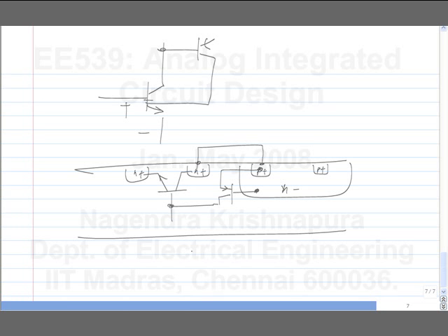If you have a large drop across this, let's say this is grounded, then this will get forward biased and that will turn the latch on. That's why as you go to newer and newer technologies, you have smaller and smaller components, but you also have higher and higher doping in the substrate so that this won't happen. Okay. So when you deliberately forward bias junctions that are not supposed to be forward biased, it could potentially lead to latch up. So only after all those reliability issues are addressed will you get these things in practice.